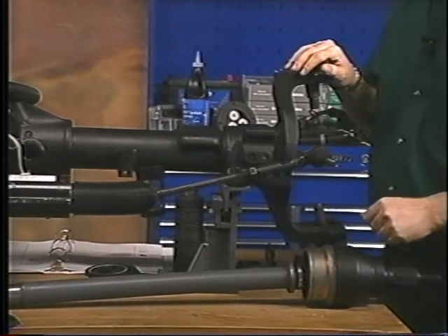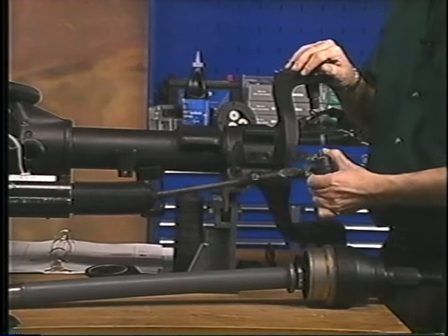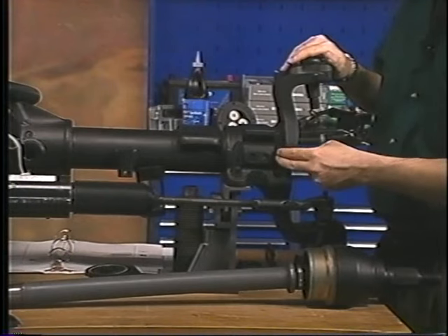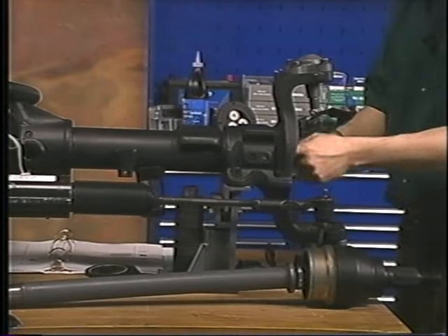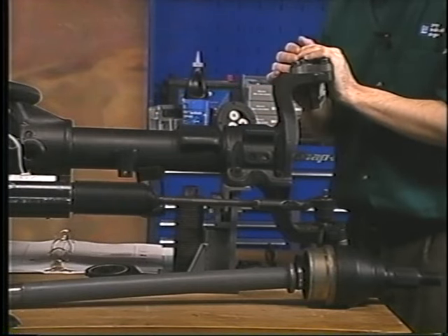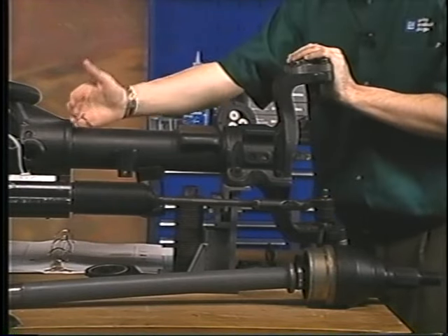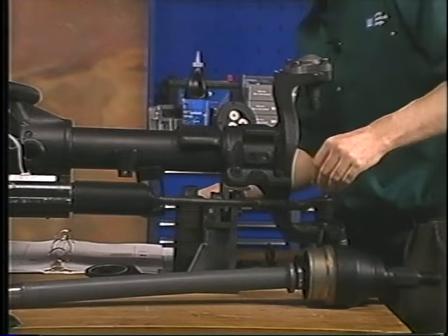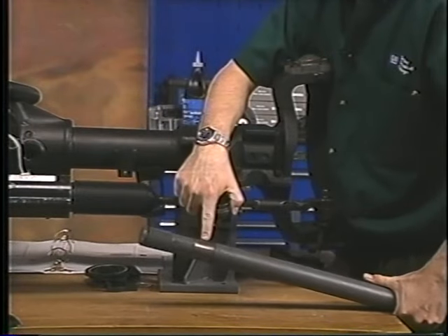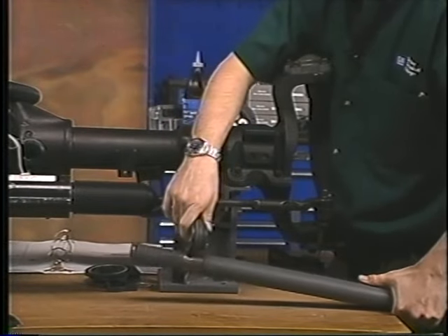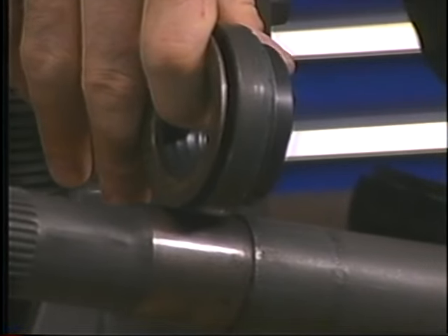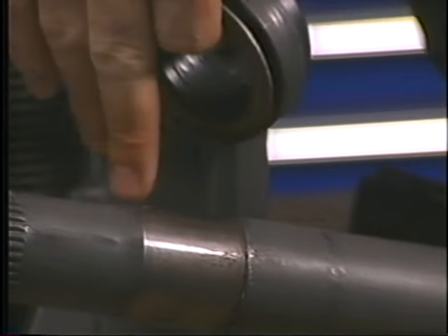Now, we want to talk about a couple of seals. We know that we no longer have a conventional wheel bearing, do we? No longer do we have a wheel bearing out here. We've got that integral wheel bearing out here. So we no longer have our rollers back here, which means we no longer need to supply lubricant down the axle shaft to lubricate the outer bearing. So I'll tell you what, let's put our oil seal right there. Let me grab it. Here we go. Look at that. That's where our oil seal rides, right there in the axle housing, right there on the polished portion of the shaft. Here are the splines. You get an idea where it's at. It's going to keep all axle fluid from this point inwards.